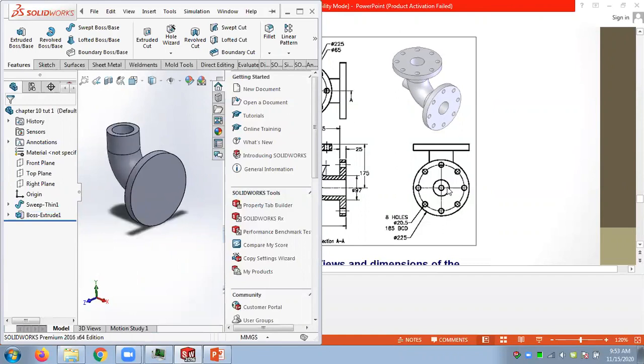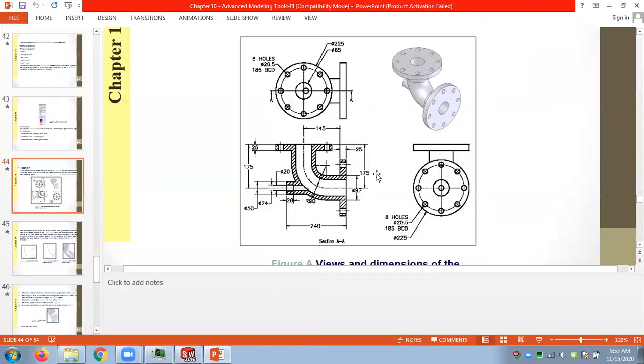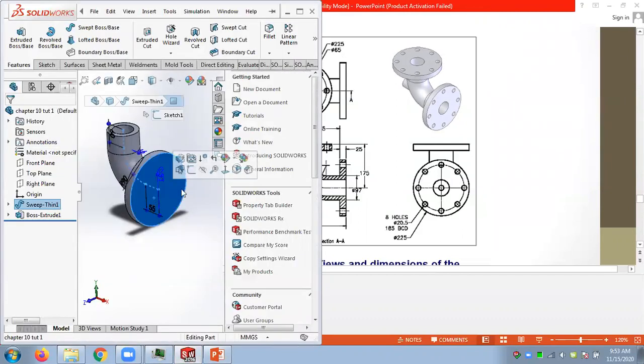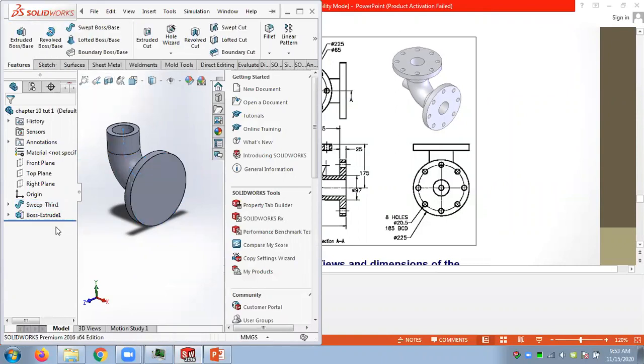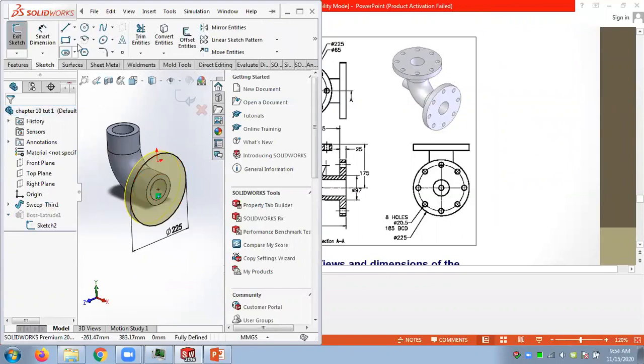Now we can draw these holes here. There are circles here and the middle hole. The middle hole is also 65 diameter, the same diameter. So I can cut that also. If you want, you can get that from the previous sketch even. When I draw this for the extrude, I can have two lines and get the middle hollow automatically.